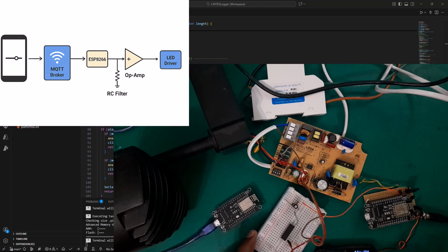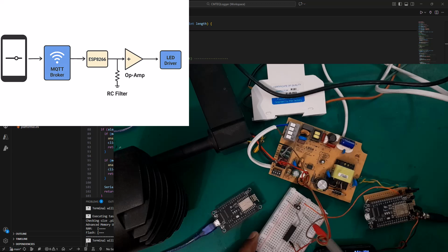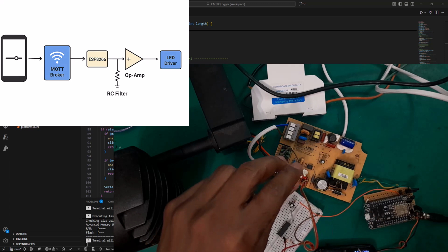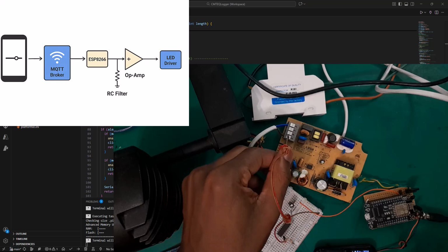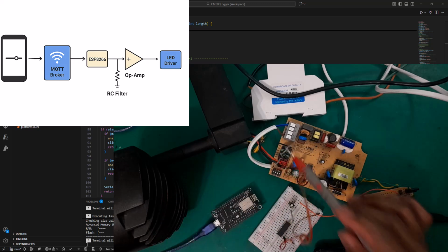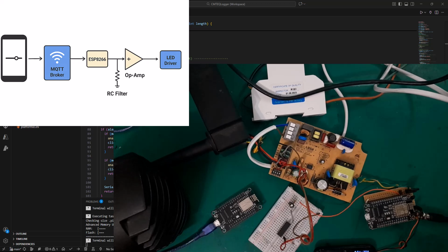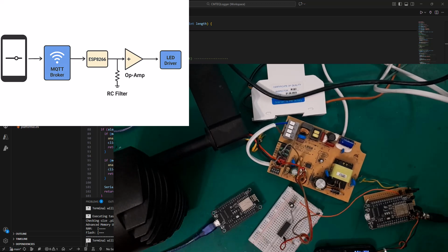And that's going to be fed here on this simple RC op amp circuit to create a 0 to 10 volt dimmer, and that is being fed into our dim plus and dim minus, and as a result the track light here will be controlled, okay?